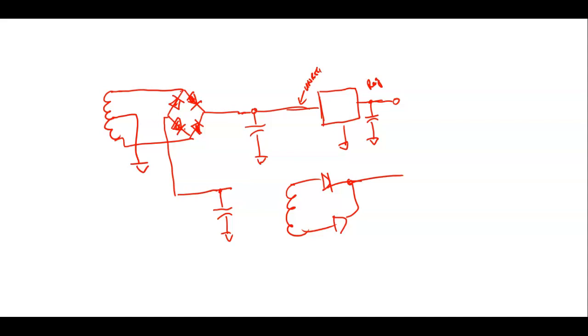If my input voltage drops down to 4 volts, it's going to go out of regulation because we designed it to handle an input varying voltage between 6 and 7 volts. For power supplies, it's going to do it over your design. You can't say it's infinite, right? It's going to try. There's no such thing as 100% regulation. So we're not going to come up with one that's got a percentage of error of 0.